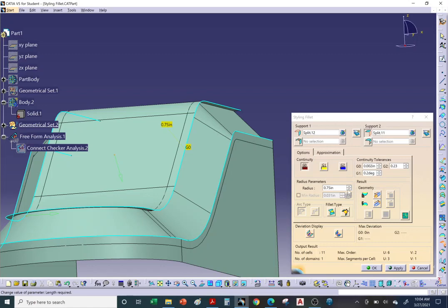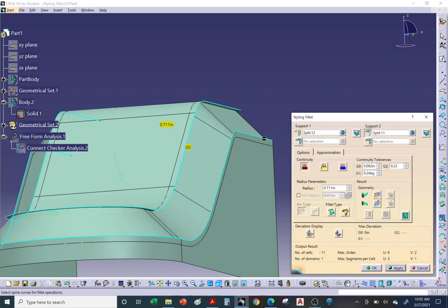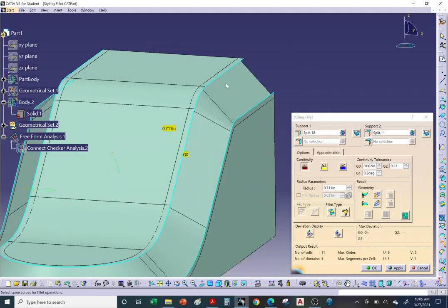If we were to reduce it, you're going to see these dark edges move as I reduce it. I'm going to hit preview, see if it accepts it, apply. See how the edge moved inward because I reduced the radius. Now, once again, we're getting a straight, and let me go ahead and hit OK. And by the way, we do have the option to trim off the excess. Okay, so any excess, it'll trim it off.